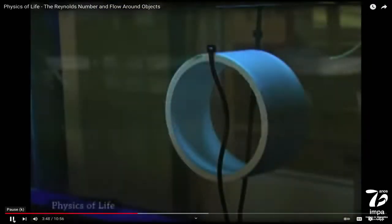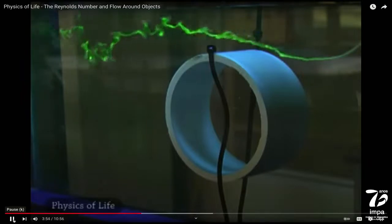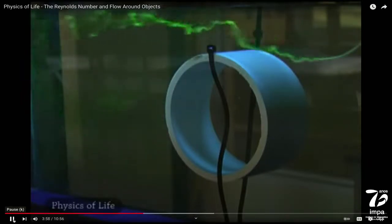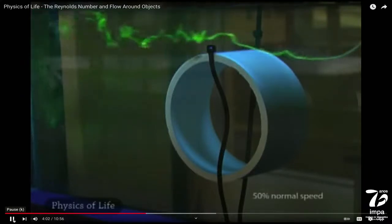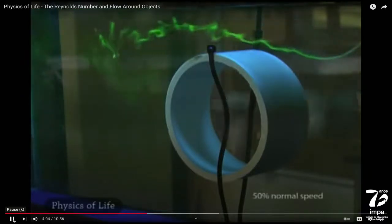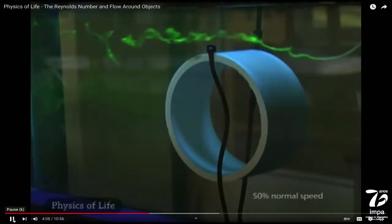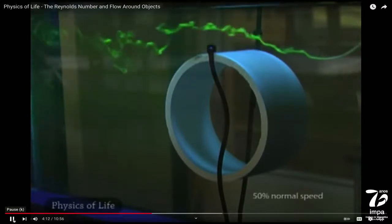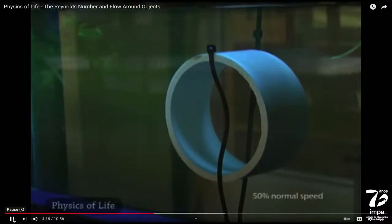We're going to visualize flow using a stream of fluorescein dye, which fluoresces bright green under an ultraviolet light. Here, we're injecting dye from a small tube positioned just upstream. You can clearly see the streamlines as the fluid flows around the large tube. You can also visualize the quite complex flows that result. Here, we're dealing with Reynolds numbers up around 15,000 or so, which is the range where turbulent flows are quite common. Let's now look at these flows a bit more closely.